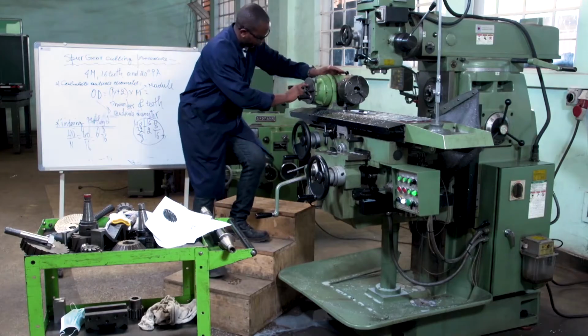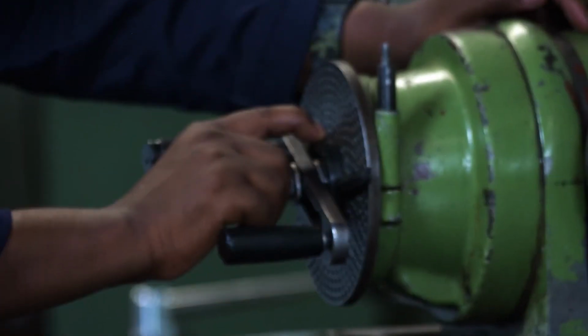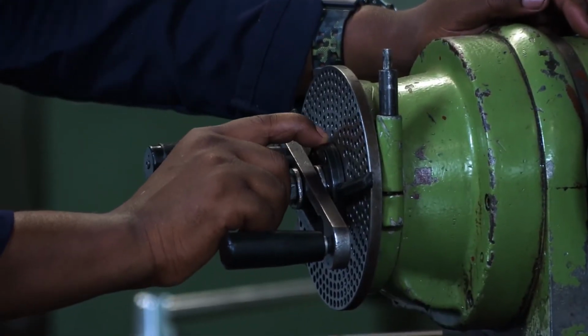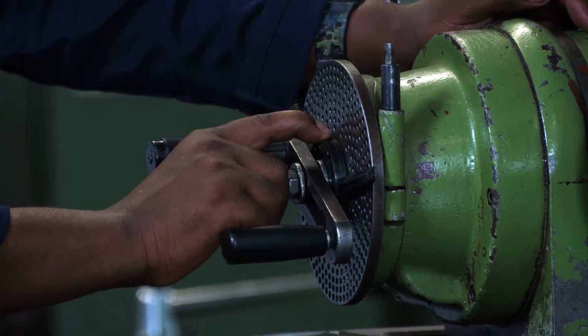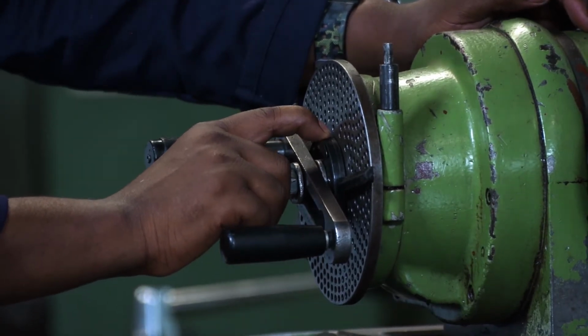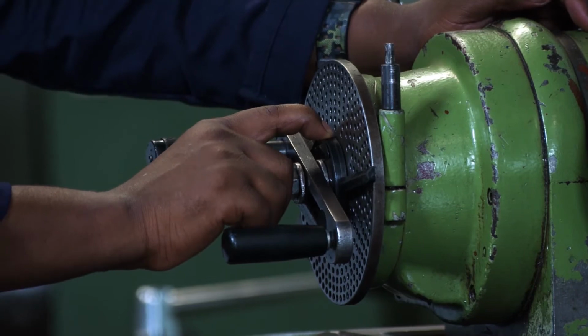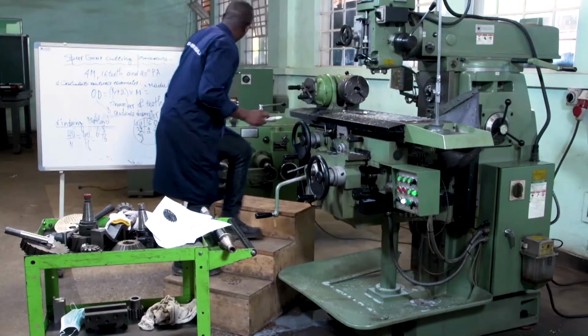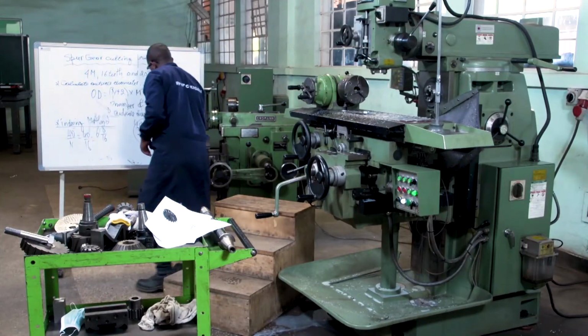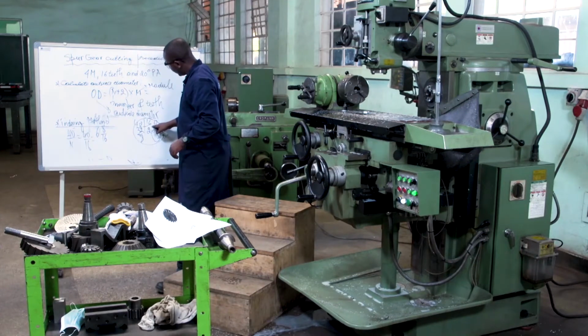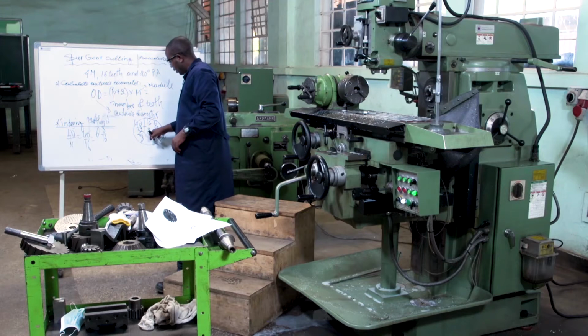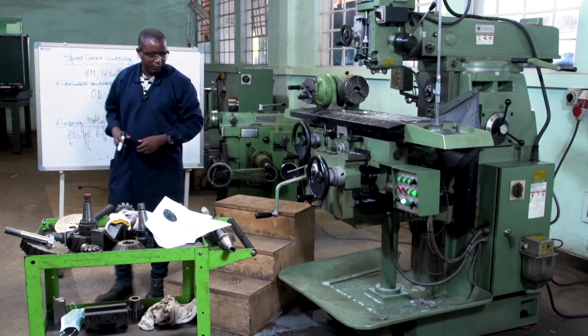You see here the first hole cycle is 16 holes. It means we have to select that hole cycle, where we have 16 holes, to add holes after a full index crank turn.